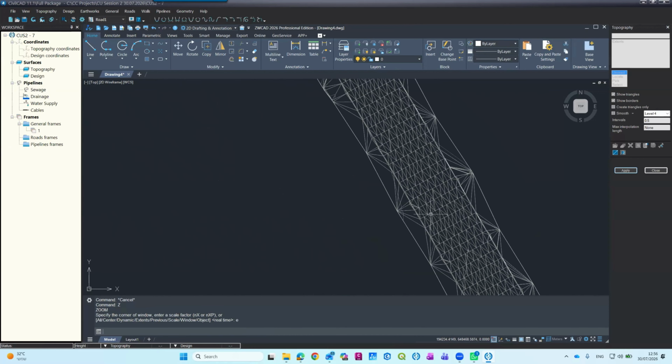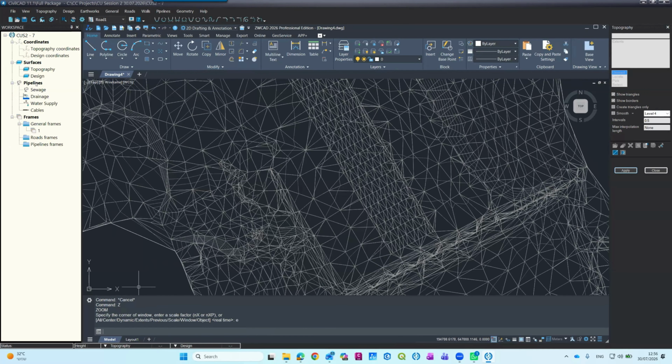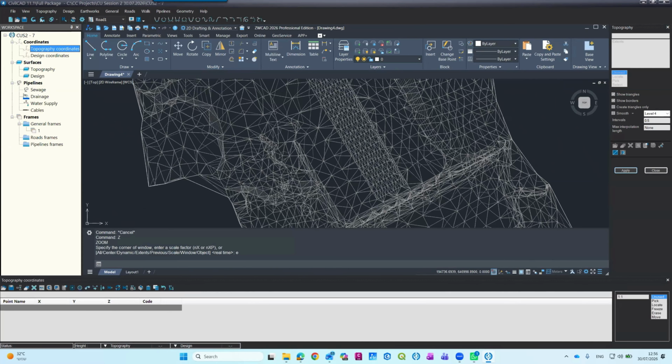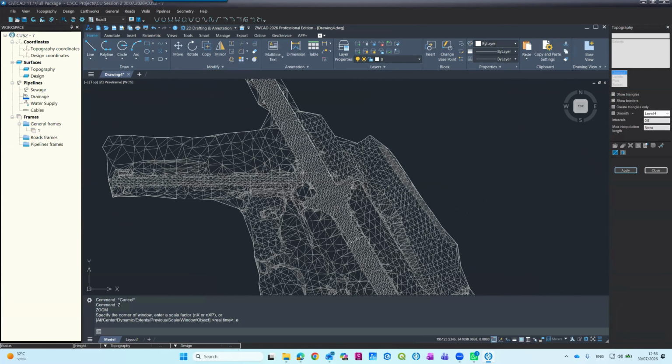That's it. Don't extend. See? Again, I received the LandXML. I can continue. It's a surface now. I can continue working on it. I don't need coordinates. I don't need to do filtering. I don't do anything. But I will need that my software will have a software that can create LandXML.